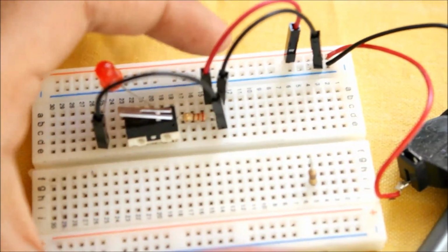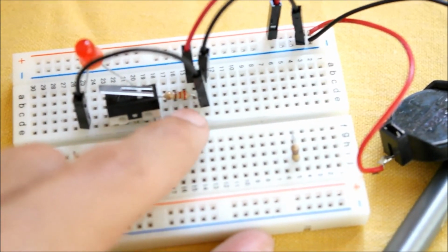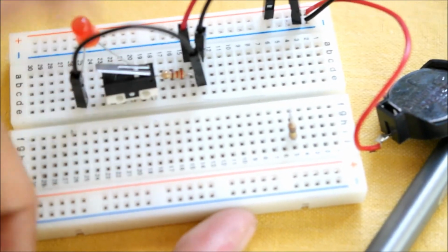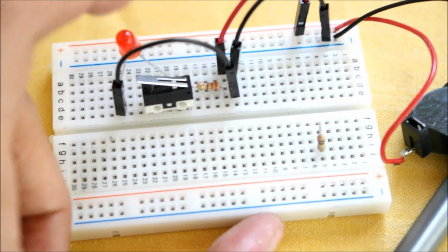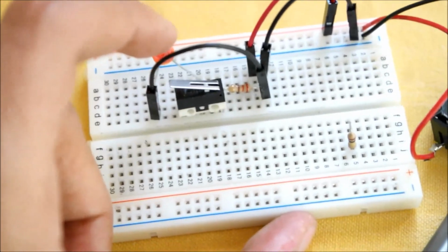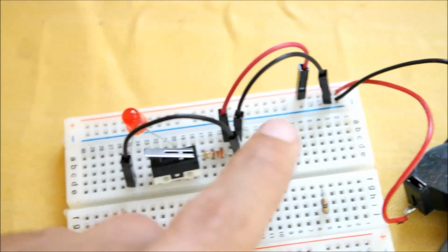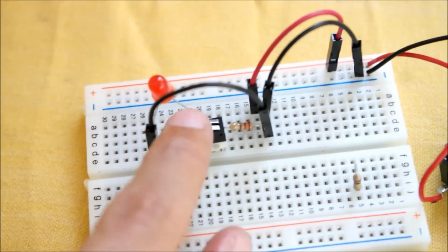I'm just drawing the positive wire, putting it to a resistor here, 220 ohms. The resistor goes in series with the switch. The other terminal of the switch goes to the positive end of the LED. Yeah, you remember how to read an LED, right, from the last tutorial. And the negative end goes all the way through the jumpers into the breadboard to the negative terminal of the battery. So now when you press the switch,